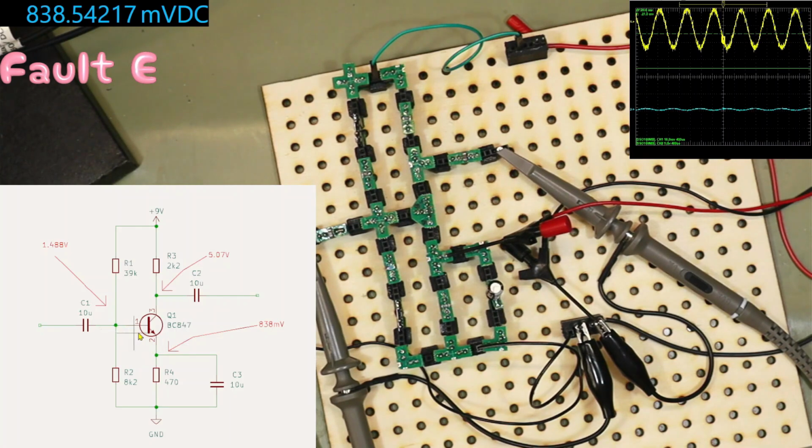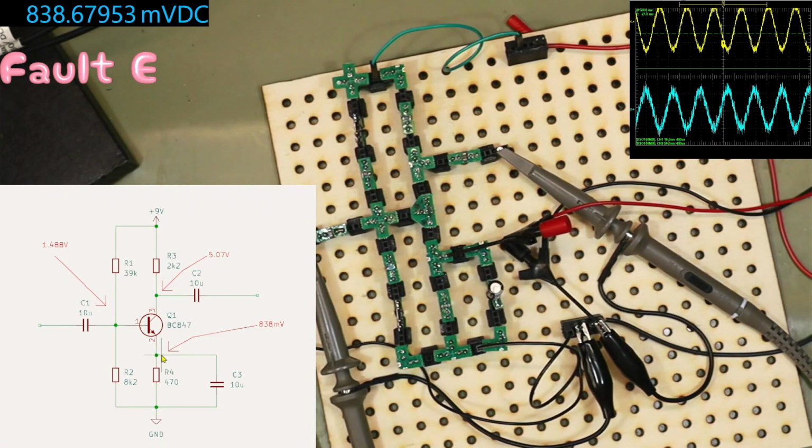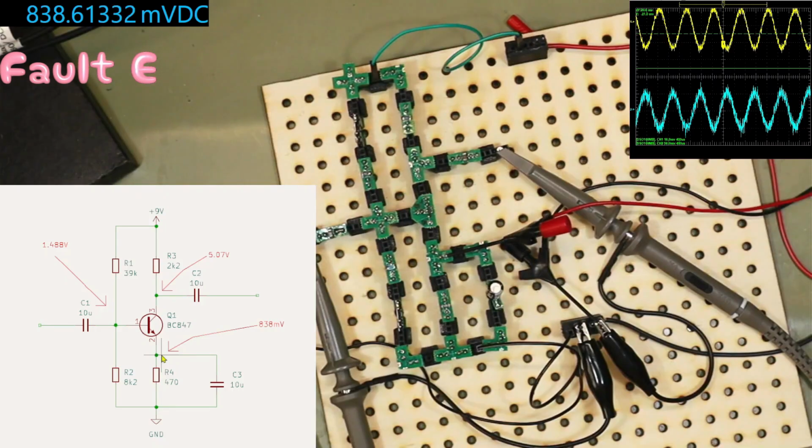We've got the right bias voltage for the base. We have the collector sitting where we want it. We have the DC conditions on the emitter resistor exactly how we want it. And we have output. You can see how noisy this scope is and why having it on averaging helps. But we are now down to 50 millivolts per division on the bottom one. So it's not just the fact that we have, let's move the trace up a bit, maybe that'll help. Oh, no, look, it's completely bollocks.